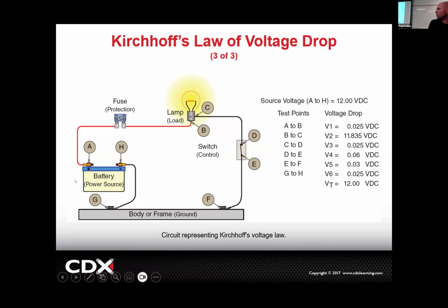We don't know if it's before or after, which is why, for me, I'll switch over to available voltage and I'll be like, how much is the load getting? And if the load is only getting 6, I know it's before. But if the load is getting 12 and it's still leaving 6 afterwards, I know the problem is after.